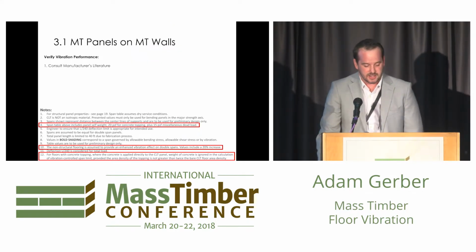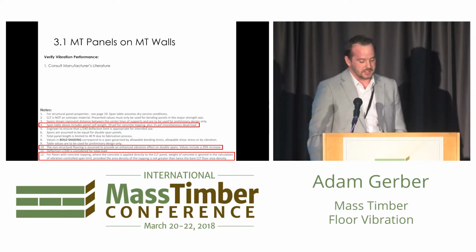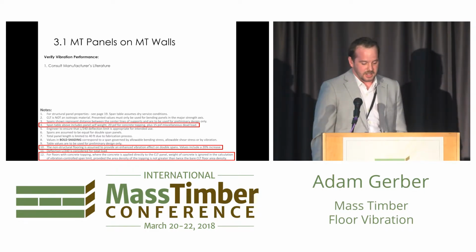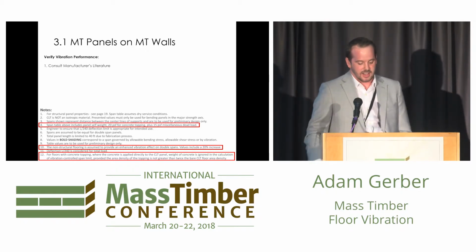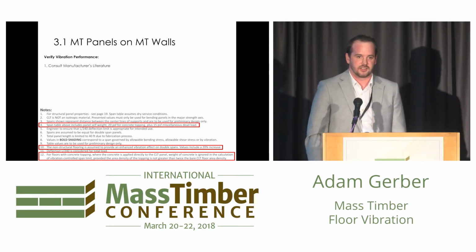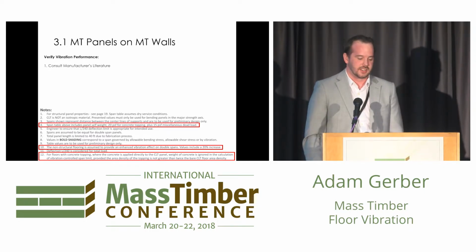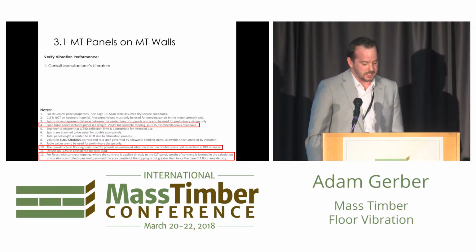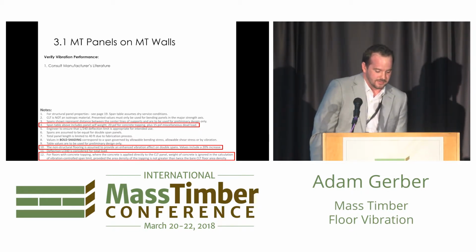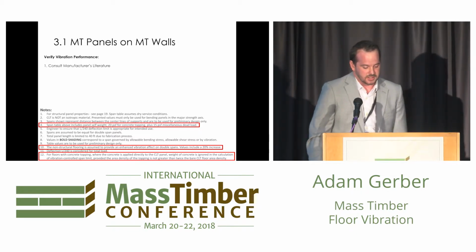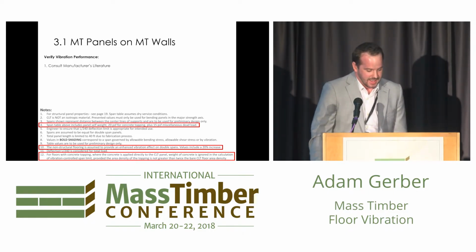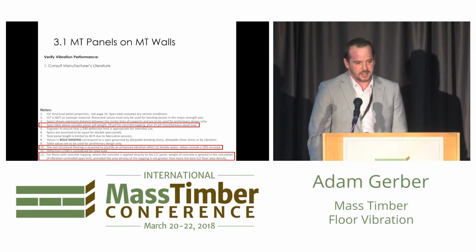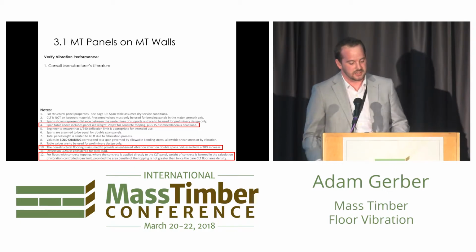And then, as with all things, we need to read the fine print. Underneath the table, there's a bunch of qualifiers to identify when it's appropriate to use those specified vibration limits, and a few interesting clauses as well. If you're going continuous, there's a 20% increase in span that you can accommodate, and you can neglect the weight of the topping, assuming it's not too heavy.